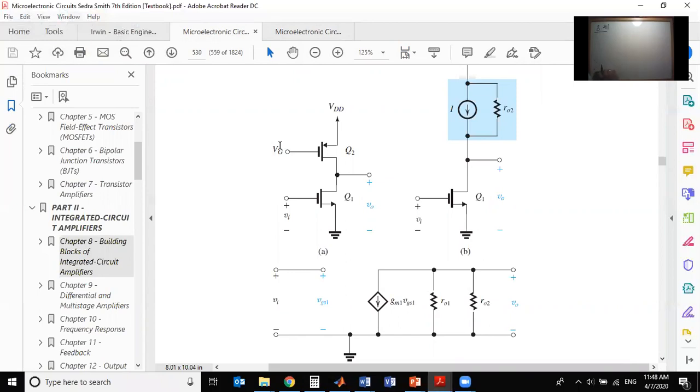I know the time is flying, so I will write it down. We know that this is a PMOS transistor, right? We know that VSG as a magnitude of the second transistor is V threshold P plus V overdrive of the second transistor. We know V threshold and we know this one. If you add them up, this is going to give you 0.75, because this is 0.5 and this is 0.25 volts. Okay, now can we find VG?